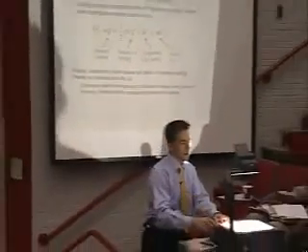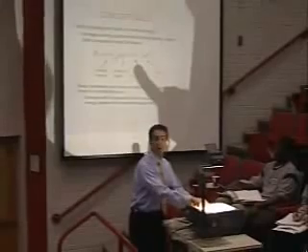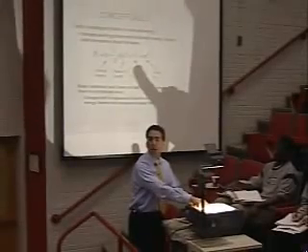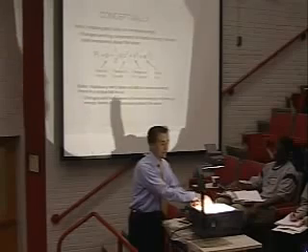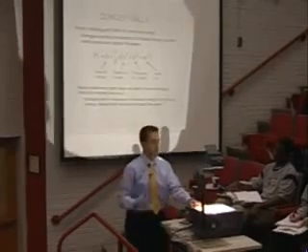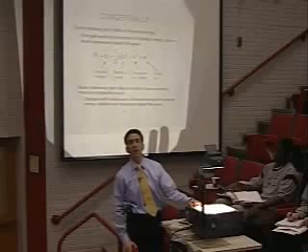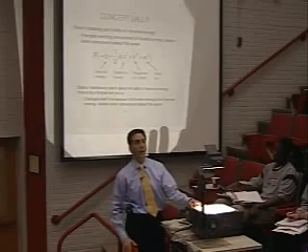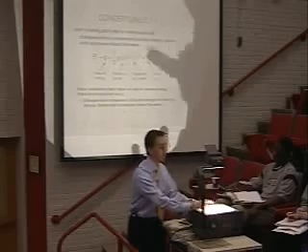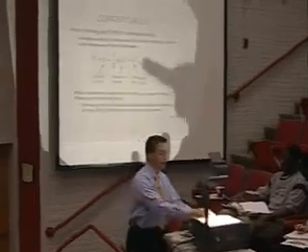So what you do is the rotor puts in swirl, and then the stator, or the stationary part, converts that swirl into internal energy. And then the next rotor puts in more swirl, then the stator converts the swirl to internal energy.